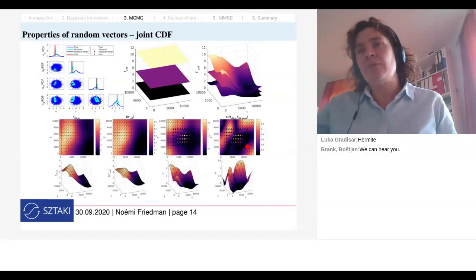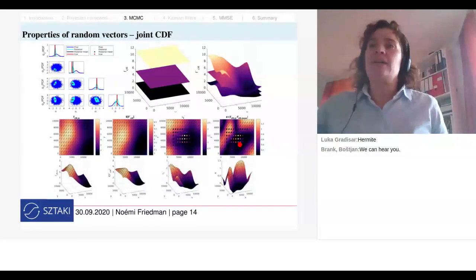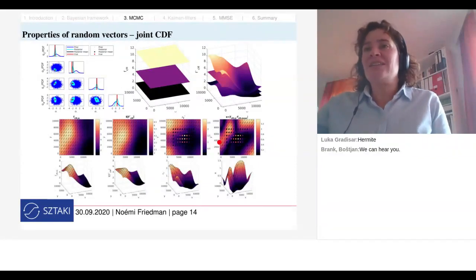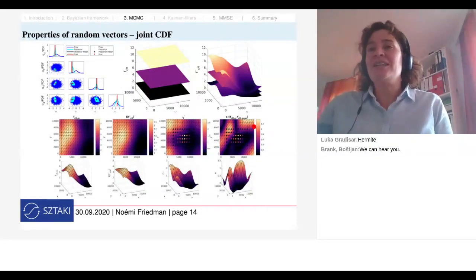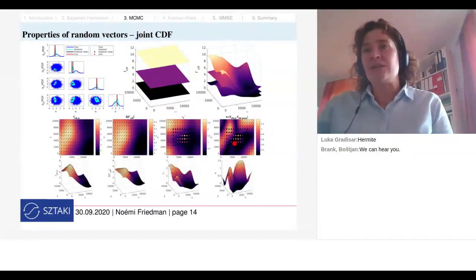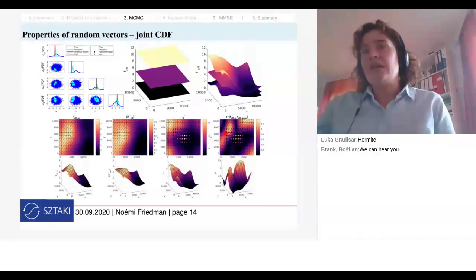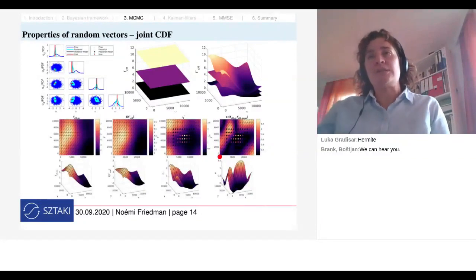So those were the 60 points that were assimilated, and their colors represent how high the displacements were at those points. So because there were no displacements here, of course, you cannot learn anything about the compressibility field in those regions where it doesn't displace, right? If you have no deformations, then you cannot learn about the compressibility. So this makes sense. So from these measurements, what I could learn is rather about this region where the error is really low, so I can get a very good estimate of the compressibility field.